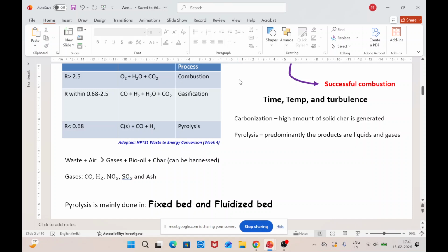As far as the pyrolysis reactor is concerned, one of the important differences, unlike in the case of combustion and gasification systems where you have a flow of air, is that here, in order to remove the pyrolysis products as well as the gases that get generated, you use an inert gas system. And in order to avoid the use of inert gas systems, you go for the ablative reactors. But as I said, they are laboratory confined, and their commercial viability is still a question.